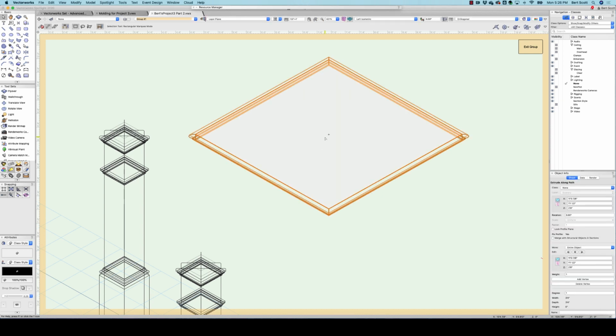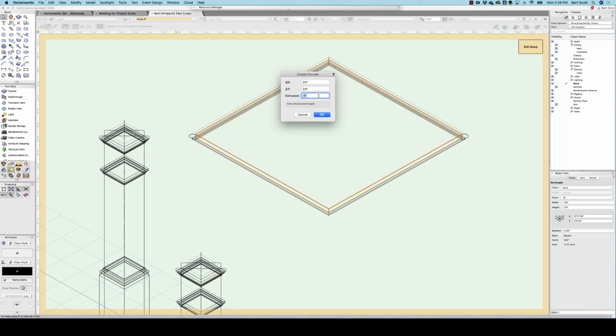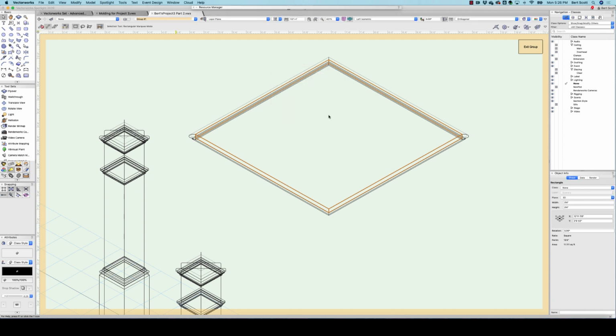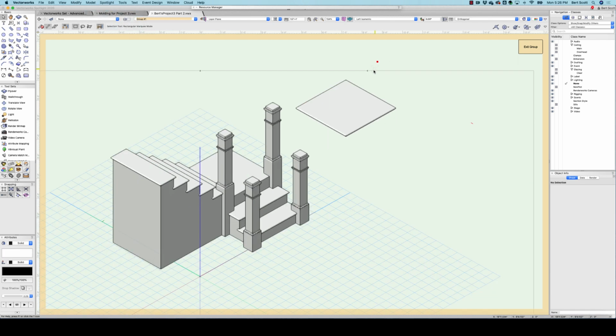We'll click OK. We'll grab our second rectangle and extrude it down an inch, and that setting is still left from the last time we did it. We'll click OK. We'll look in OpenGL and make sure everything is good. We'll select both. Then we will Model, Add Solids. So far so good. So then we're going to go back to what view do we want to do this in? Let's do this in top.